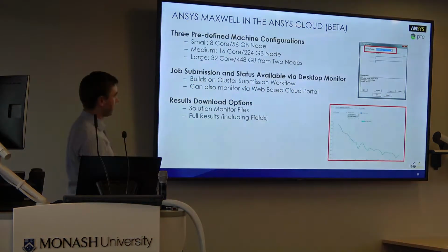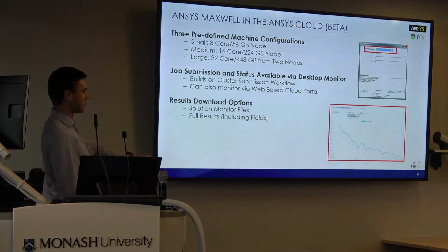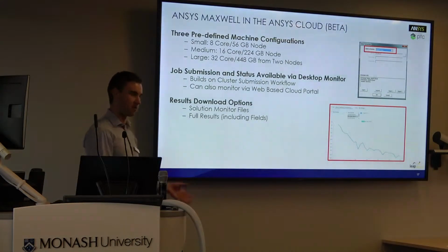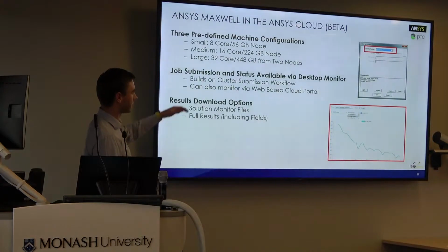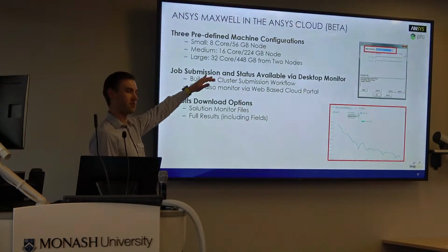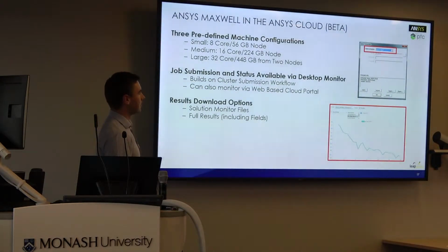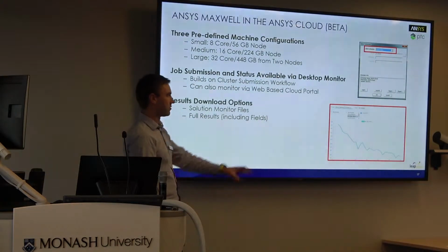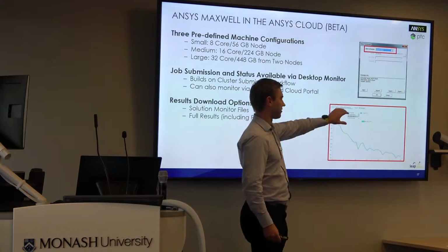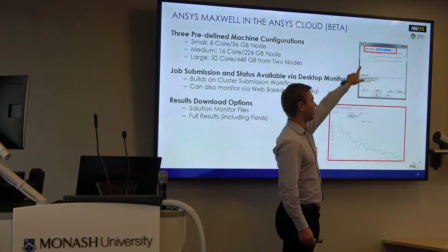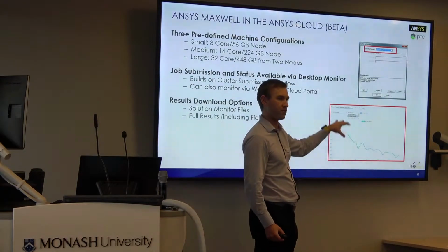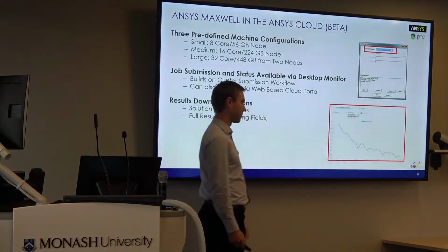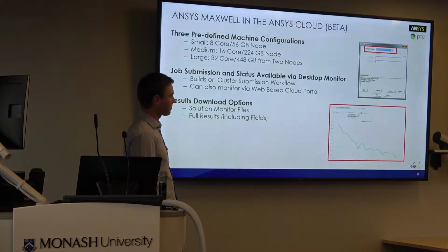modeling. Moving into usability, everyone loves talking about the ANSYS cloud at the moment. For Maxwell, it's still in beta, so we're missing a few post-processing options, but on the whole, we use the same predefined machines as we do for HFSS, which tends to be on the RAM-heavy side and fewer cores. We use the same submission scheduler, so it's a case of logging into your cloud account, choosing ANSYS Cloud, and pushing OK. And then you can access all the post-processing while it solves, either through the web or through your phone.